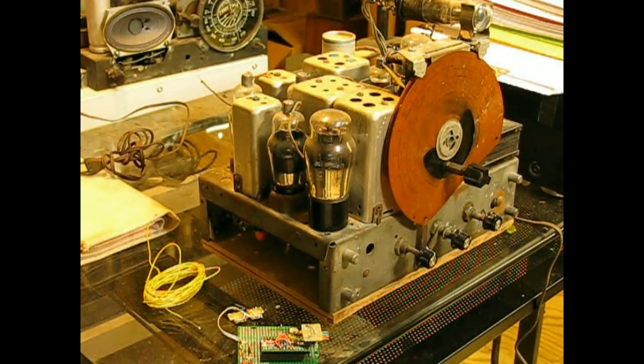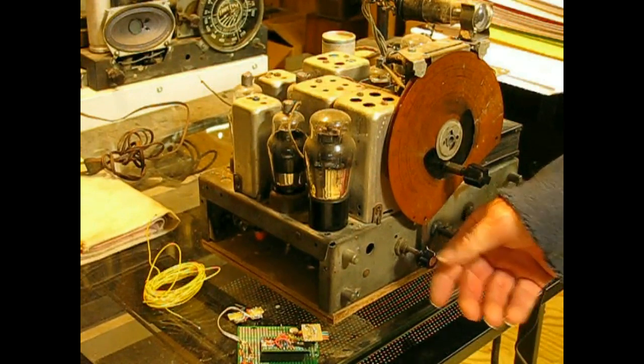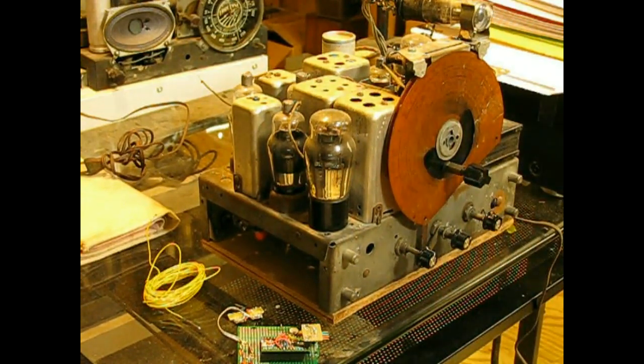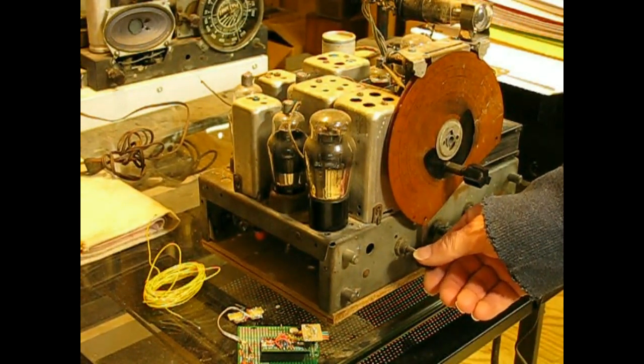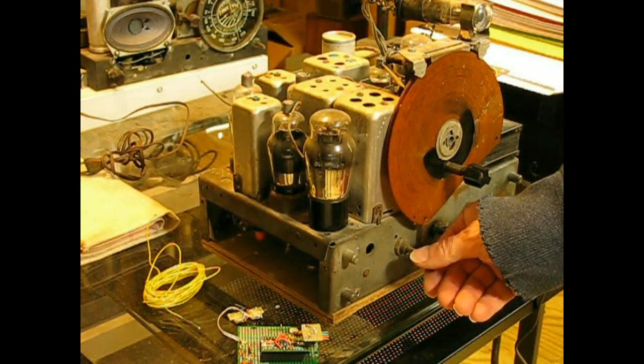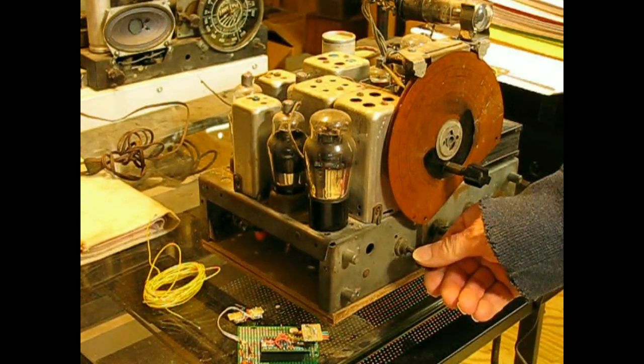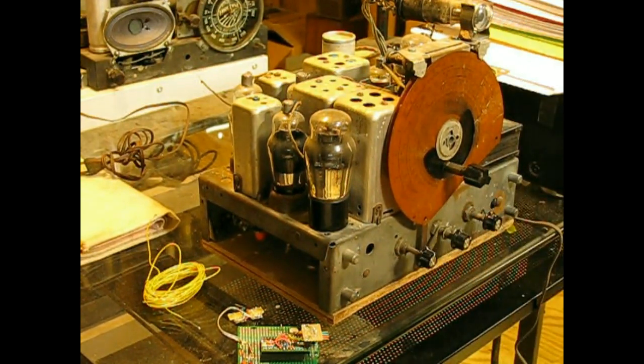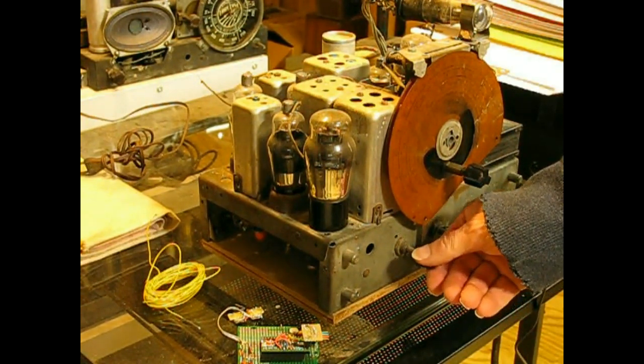It's AM plus shortwave. And what I'm going to do is, it's tuned to a station now, and it's about 11:30 on a very cold night, so there's a lot of skip. That is signals coming in via the ionosphere. And what I'm going to do is put my finger on the local oscillator capacitor, changing the capacity a little bit with my body, and tune in a different station, and that should make it very clear as to what this drift is all about.